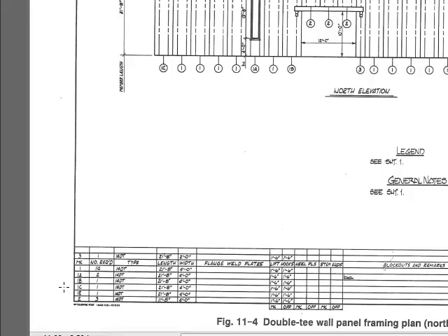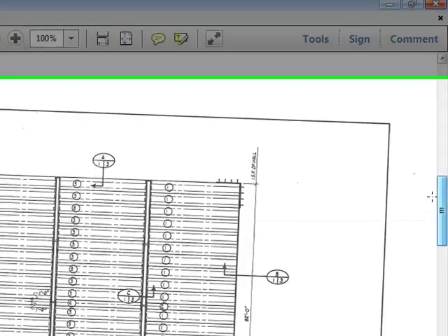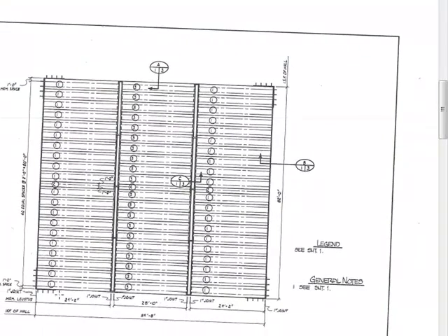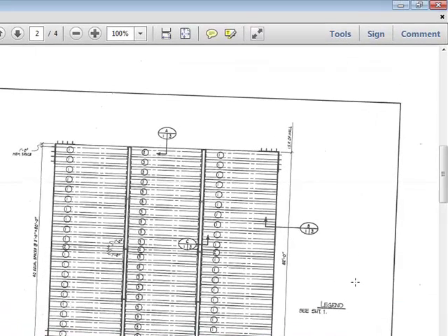Then you would start drawing your beams and then assign the marks, complete the schedule, and, it says, examine each place where a beam rests on a column and assign letter designations for each different situation. So if you look back up here on the screen, for instance, you got all your ones over here. Well, these are the same thing, but it's opposite hand. Remember that? Because it's opposite view. And then it goes on to talk about, and you need to read this because this is stuff that would be on your quiz, the roof and the wall, and then that information.